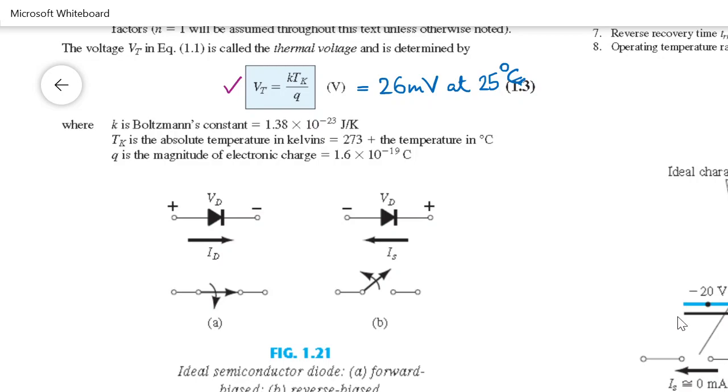What happens in the reverse bias region? In the reverse bias, only a reverse saturation current is there, which is very small. As you can see, this black line is very close to the 0, very close to the horizontal axis. So, a reverse saturation current flows in the reverse bias condition. So this is the diode characteristics, and we had explained that.